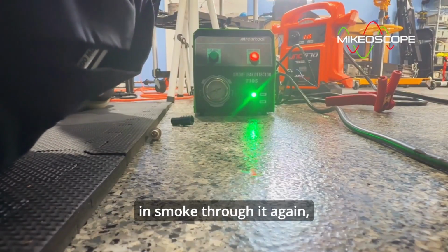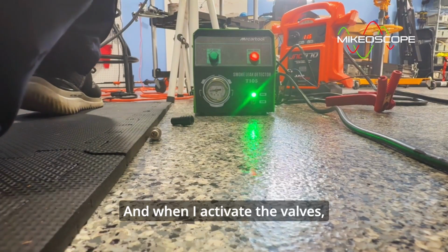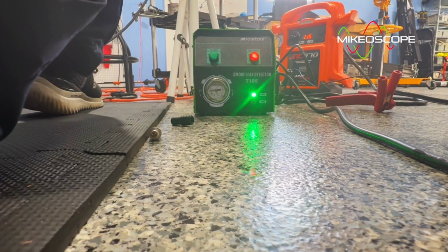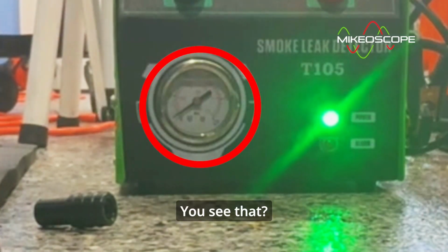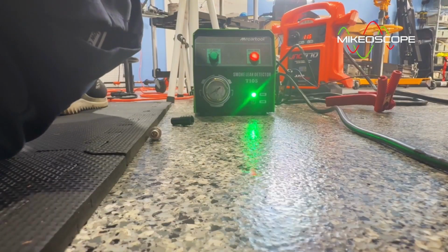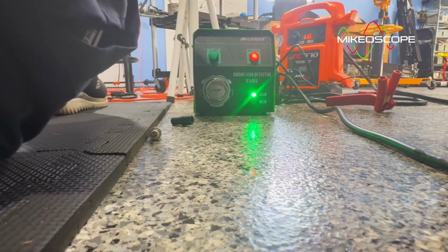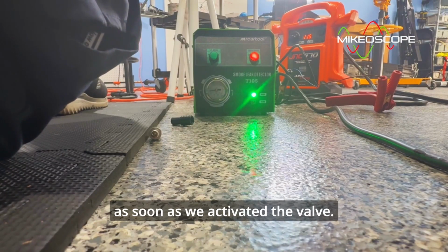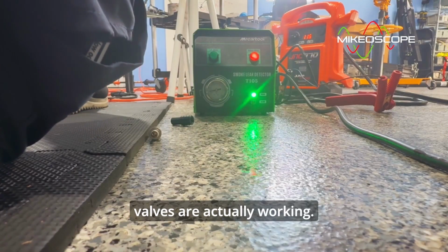So we are back to putting smoke through it again, but this time we are gonna go ahead and activate the valves. And when I activate the valves, we should see the pressure drop. I'm gonna do that now. You see that? The pressure dropped. So if we let this go for a while, we should see the smoke at the tailpipe, okay? You saw that the pressure dropped as soon as we activated the valve. That shows that the valves are actually working.